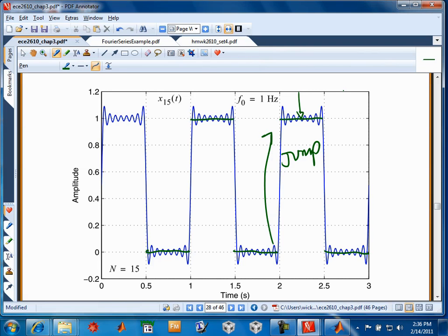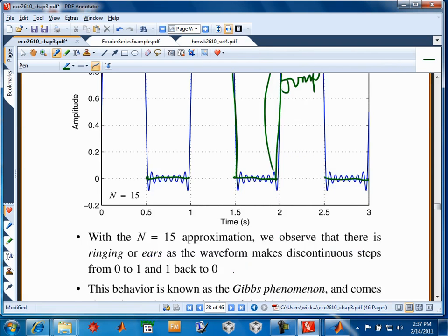We still can have ringing, though, when you try to represent a square wave without all of its harmonics, but it's going to be to a lesser extent than this, because instead of having the perfect jump, we end up having something that actually has a finite rise and fall time. So there's actually a transition in there. If it's a slow clock, we'd have to zoom way in on it to see the edge transition, but there's actually a slope there that's finite rather than being infinite.